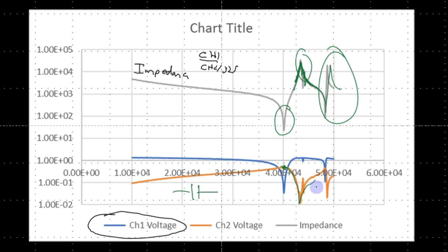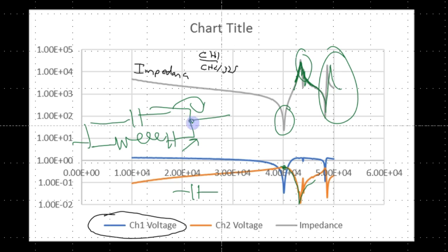Anti-resonance is a sort of parallel resonance between the clamped capacitance and the LCR branch, and I've already described this in other lectures. Basically, the current coming out of each of these sides cancels and makes it 0 or very close to 0. Therefore, the impedance is very high and the current is very low.